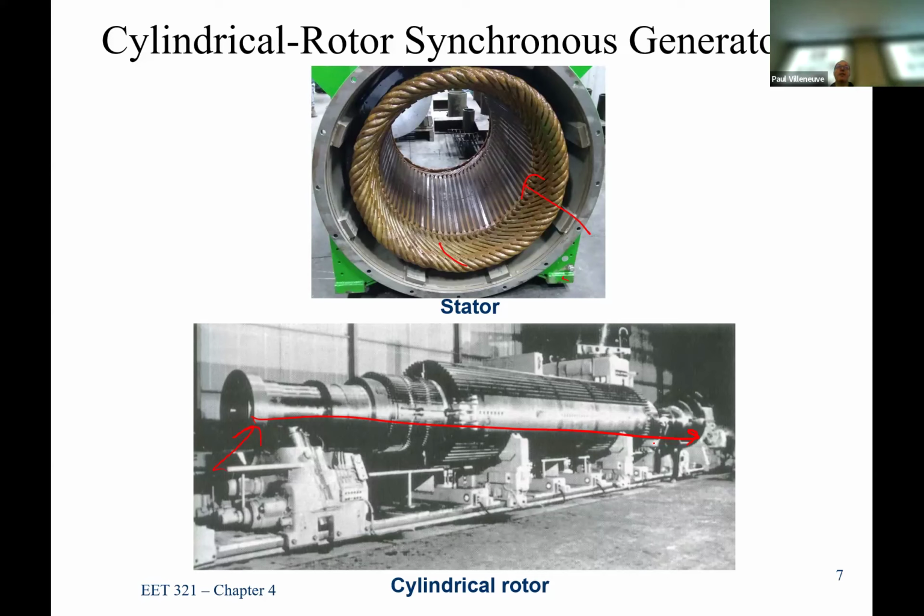Electrically, it would work fine. There is also talk about magnetically levitated bearings, where you could magnetically levitate it. But just think about the weight. This is massive weight. You need a lot of magnetic field, and inside the machine itself are magnetic fields. So now they're starting to interact with each other. Are they going to give you the performance you expect out of your machine? It becomes an issue.